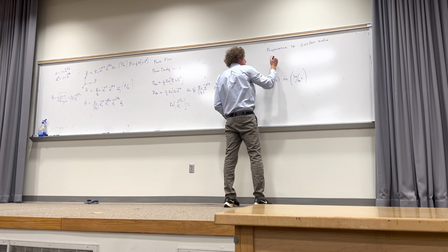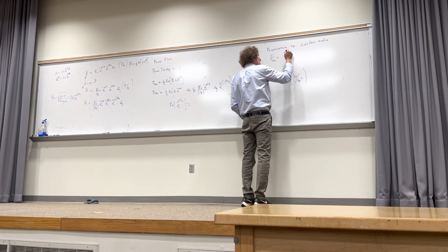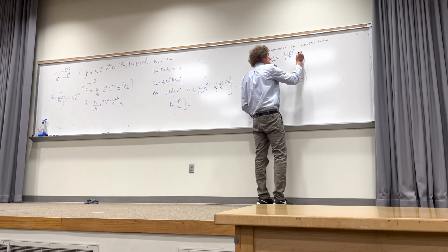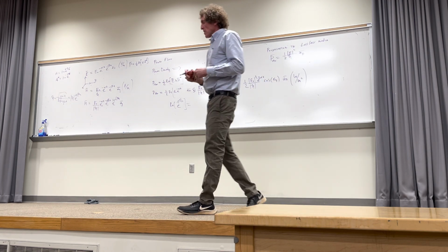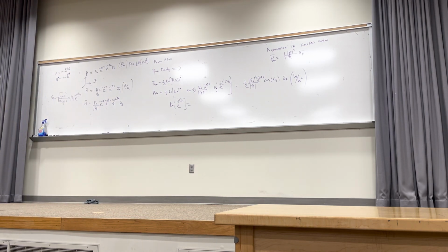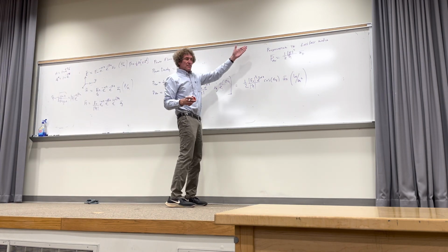then the average power density simply is going to be 1/2 times the magnitude of E squared divided by eta, if it's lossless. And it will always be in the direction of propagation, AP. The energy propagates and the wave propagates. So that would be in watts per meter squared. Now that's just power density. If you take a look at this, that's a lossless medium.